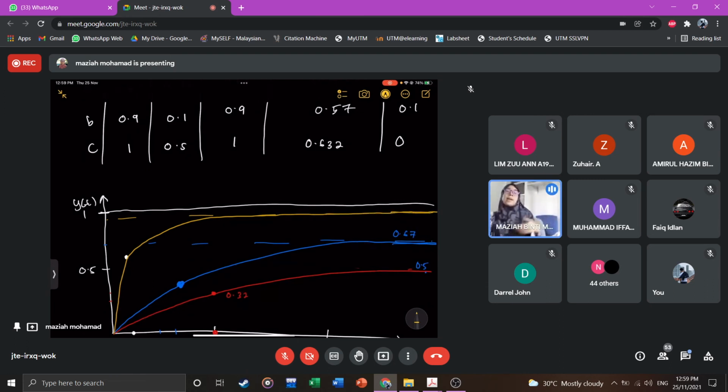All right. So by increasing the P controller, we can see that the response becomes faster. Now it takes 0.1 second, and it also reduces the steady state error to 0.1, from 0.5 becoming 0.33, and then becoming 0.1 when we increase the value of P controller.